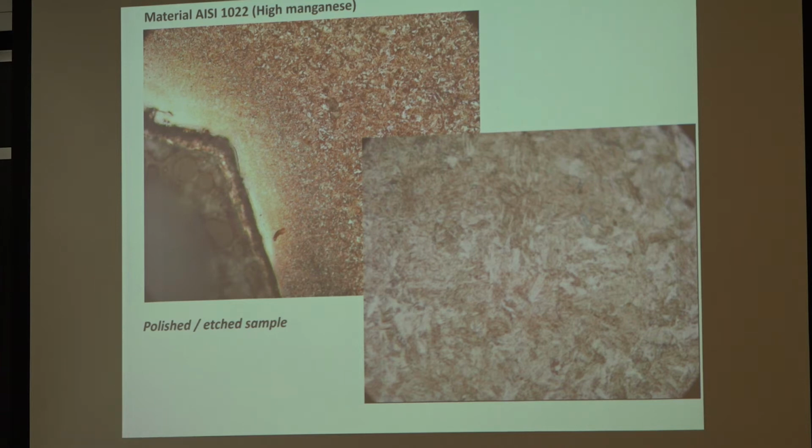So what you find in the microstructure, and that's something we'll talk about a little bit earlier, is it's a tempered martensite on the inside. But on the surface, it still is the martensite. And the reason is it's got so much carbon in it that it just stays harder. So it's in what we call the Rockwell C range. It's very highly resistant to wear. And so that's a good application for making a drill bit that is also your permanent fastener.